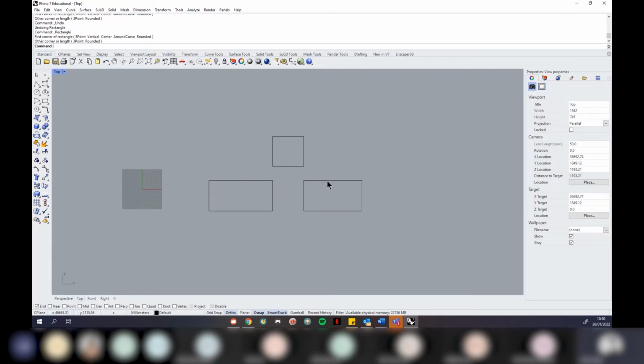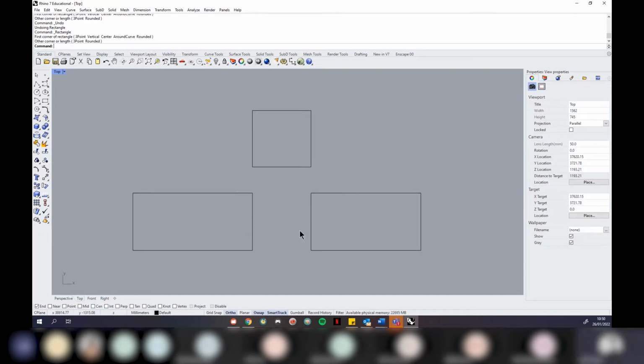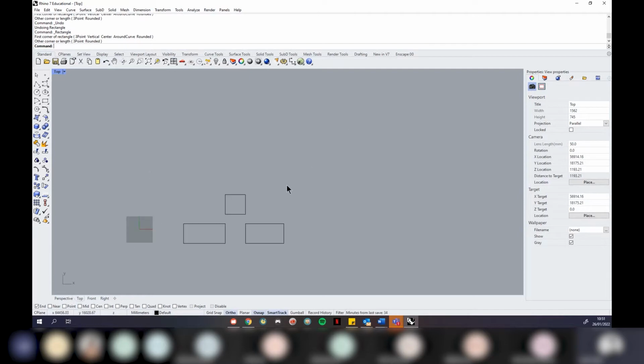If you've got a really complex floor plan with lots of complicated geometry, let's say, for instance, you're doing an entire floor plan of a building, you've got tons of furniture, basically just everything in there. Essentially, that means you're going to have tons and tons of smart suggestions, and that's going to make your drawing an absolute nightmare to work with. So if you've got tons and tons of geometry, it's going to be trying to guess what lines you're trying to draw off, especially if you've got millions and millions of curves, in which case, at that stage, you probably don't want Smart Track on. Unless you're isolating objects, you know, it might still be useful, but typically with more complex drawings, you won't be using Smart Track.